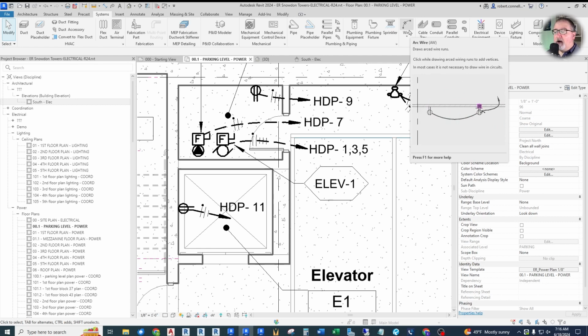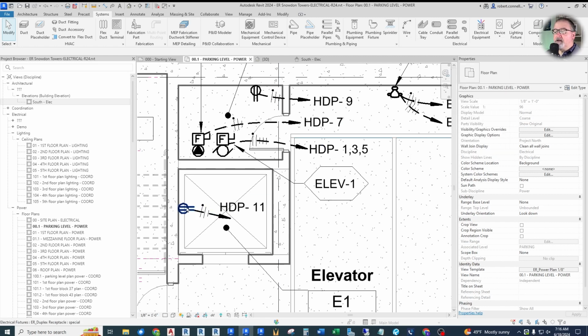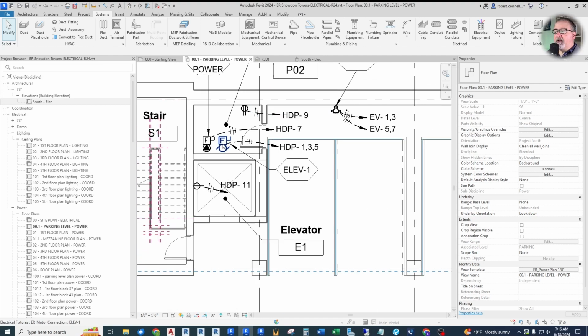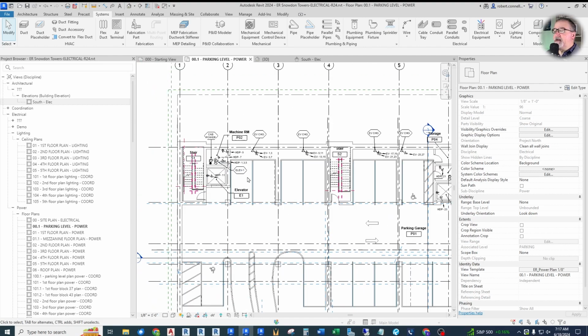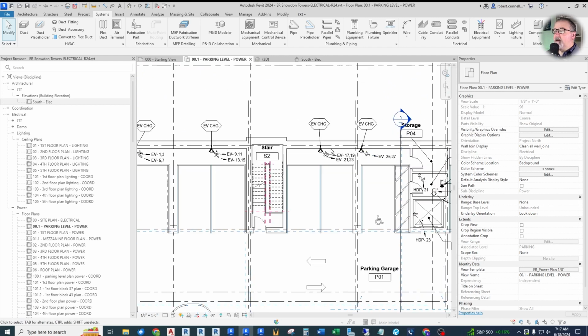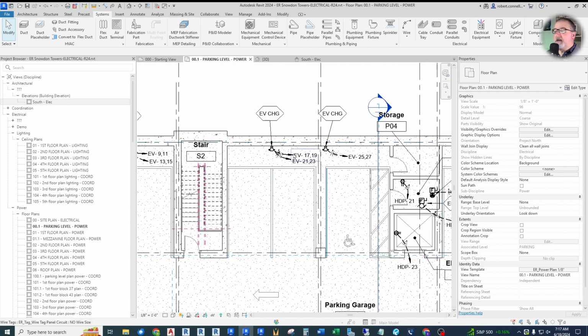It's not a single wire. It is a group of wires, a bundle or a cable or a conduit of wires. So this represents multiple wires. And also I would recognize that not everybody shows wiring like this. Many people will just show the home run next to this receptacle and just leave out the arcs. So I fully understand that there's two different ways of doing this. In my case, I still like to show a lot of arcs. I think it lends some clarity to the wiring.